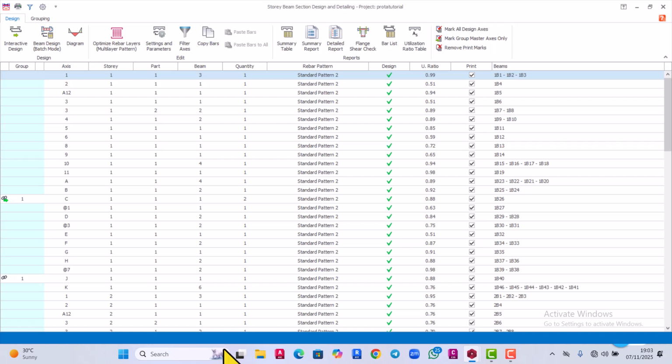Almost all parts of it are going to rest on the block. So for that plain beam, 2Y16 up and down is going to work. So I don't normally waste my time looking at the plain beam.